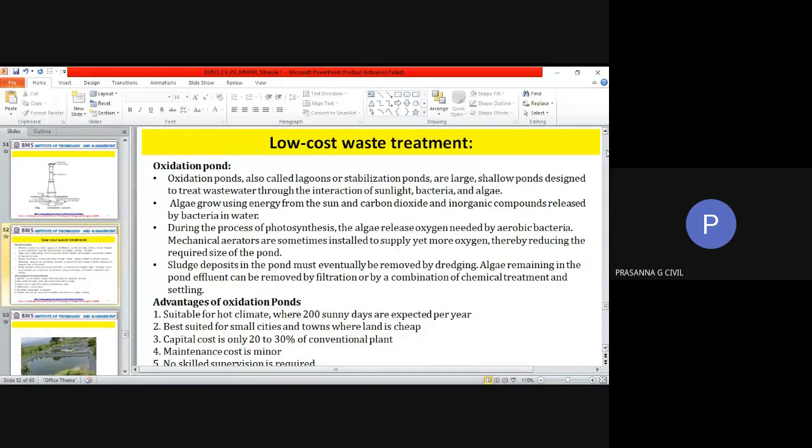Plus at the same time there are algae and microplankton, phytoplankton which are growing in the water, even the microbes, which can utilize the oxygen that is getting exchanged between the liquid and gaseous medium, and the presence of sunlight is able to actively use up the organic content which is present in your wastewater and degrade them. So it's better to keep the pond at a shallow level, 1 to 2 meter depth.